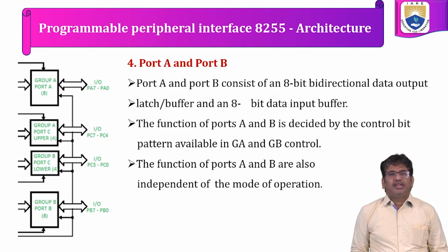Next, port A and port B. These two are 8-bit ports. Port A and port B consist of an 8-bit bidirectional data bus, so we can use them as an input port or output port by programming.